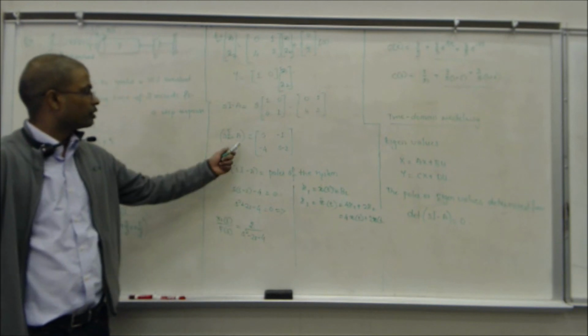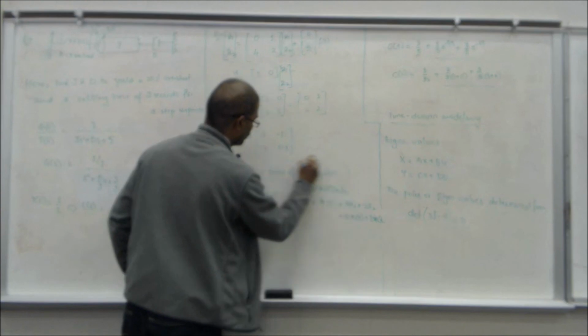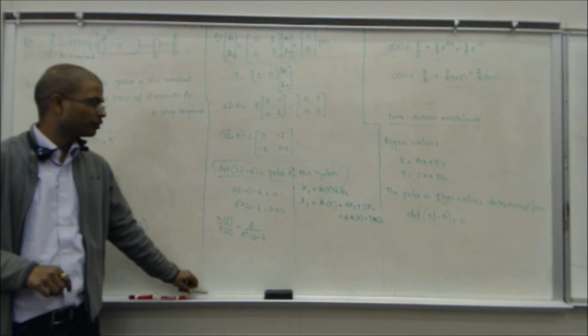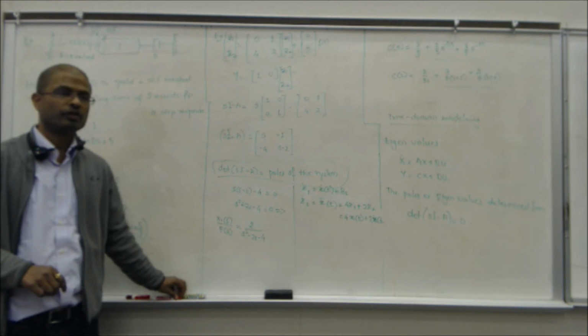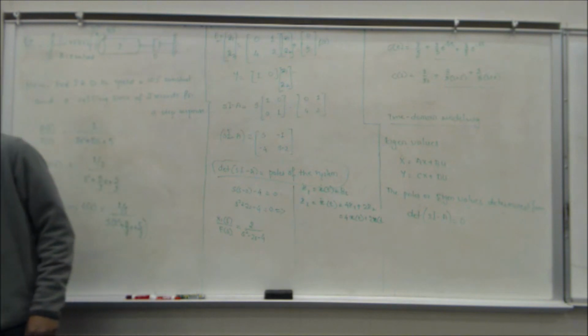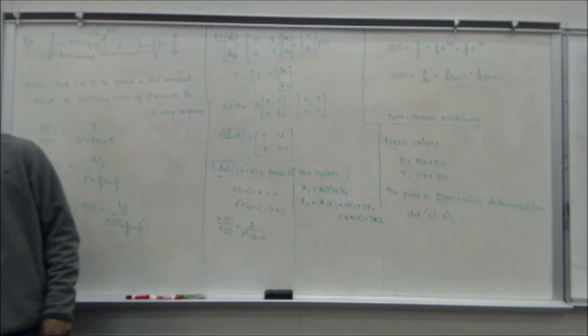But this is important, and I want you to make sure you understand this. The determinant of sI minus A will give you the poles of the system. We'll discuss a little bit of this on Tuesday.